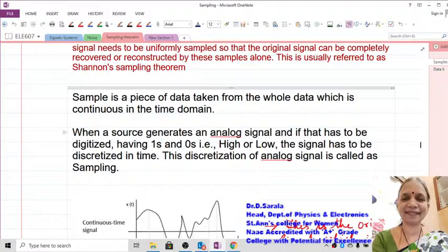The information in the computer is in digital form, and if a person on the other side has to listen to what you say, the digital information has to be converted back to analog. So initially you need an analog to digital converter. Then after it is sent, digital has to be converted back to analog, using a digital to analog converter. This is how the signal is modulated, and we call this a modem. That is what we all use in our internet systems, modulation and demodulation.